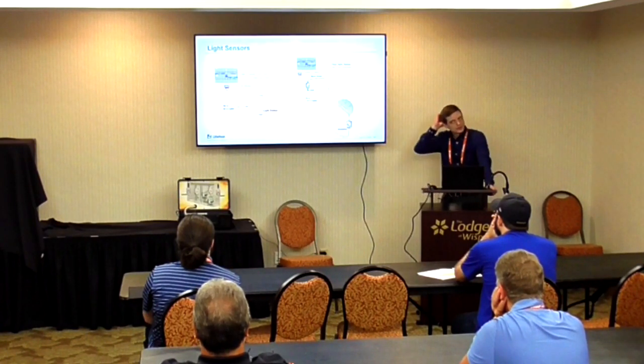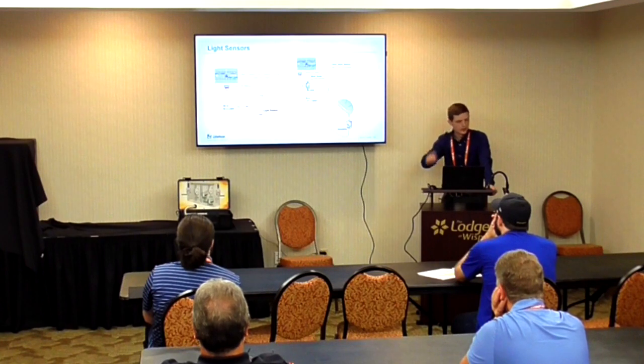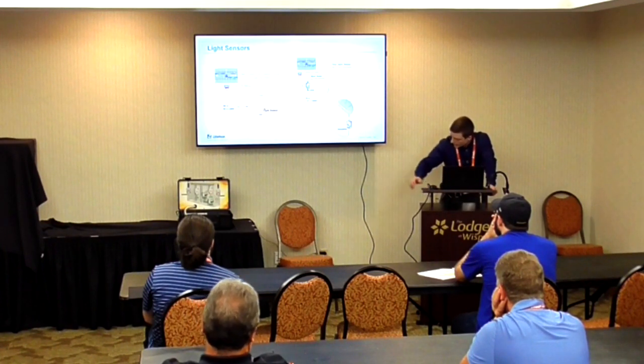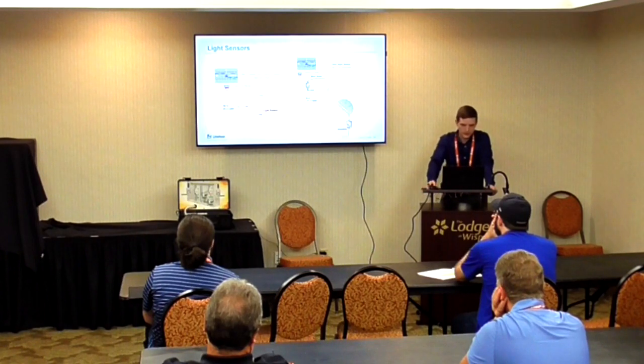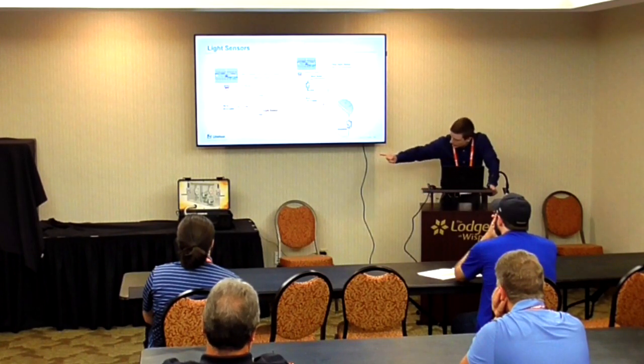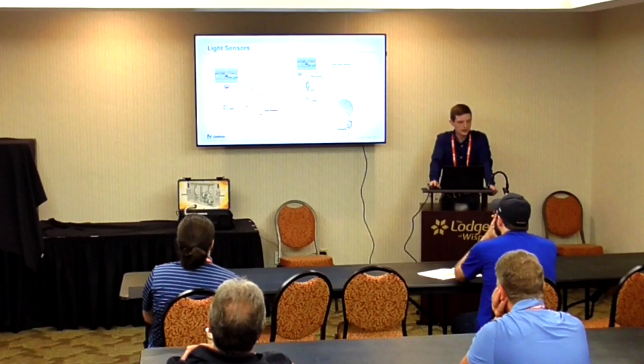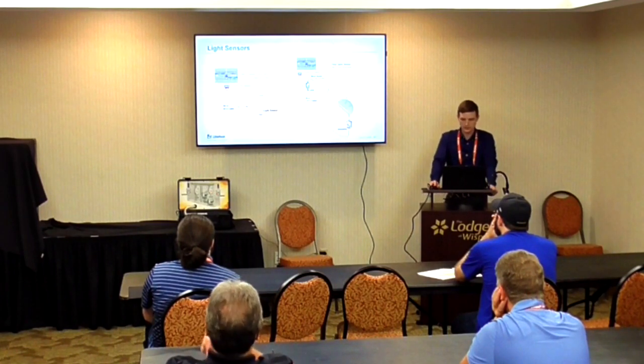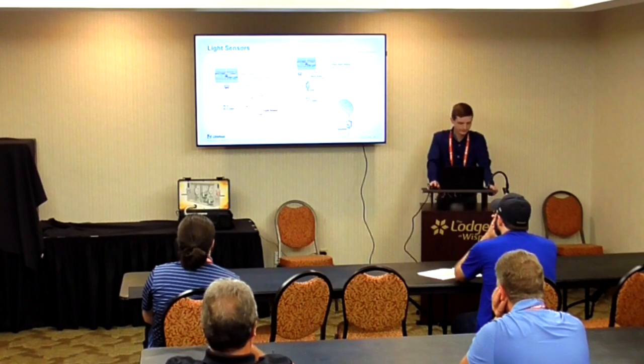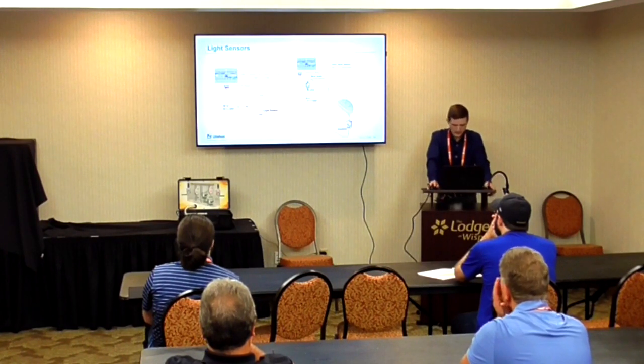There are two typical sensors that you'll see used with arc flash relays. You'll see point sensors, which is what we have, the blinky guys there, and then you'll see a fiber optic sensor, which is that string that runs across the top. The point sensor is a 6-foot cone that extends out, and it's about 12 feet wide. You'll see this oftentimes used in panel boards and MCC buckets, anywhere where you have a tight fit.